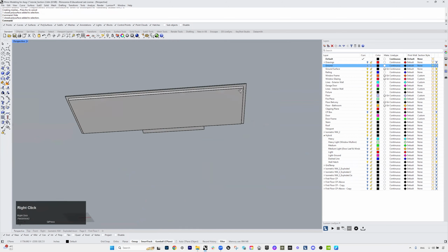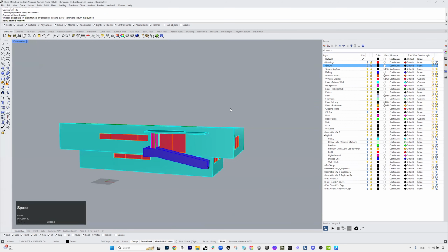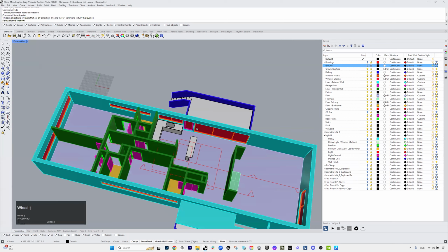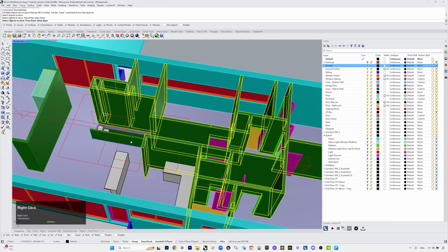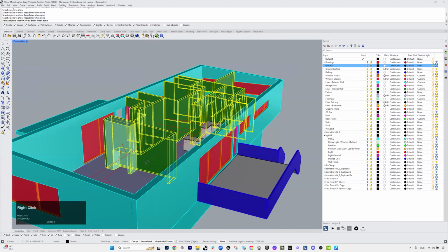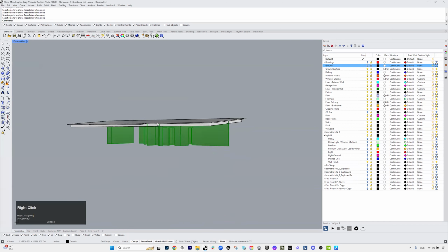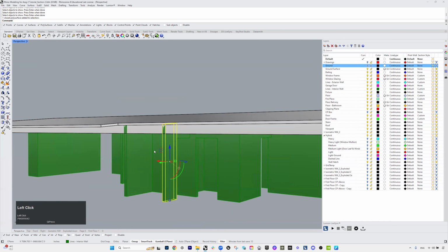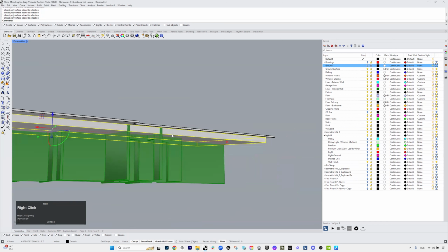And that's kind of like what I wanna do over here. So next I'm going to type show selected. And I'm going to select all of these interior walls that reach to the bottom of the roof structures. So I think these are what we have over here, and enter. So now there are these vertical walls and this roof is actually intersecting with each other.